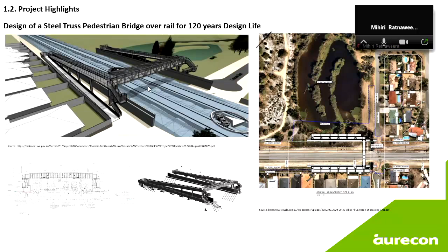So in this project, we had a steel truss, the main truss spanned over the rail, and the single span is about 44 meters, as you can see here. Now, the challenge we got during construction was the procurement of the steel truss. We can build a 44-meter long steel truss by welding the square hollow section together. However, you won't be able to achieve the hot dip galvanized coating because the facility can only accommodate up to 16 meters. Therefore, we had to divide the main truss into 3 segments with splice connections. So that adds quite a bit of complexity to structural design.